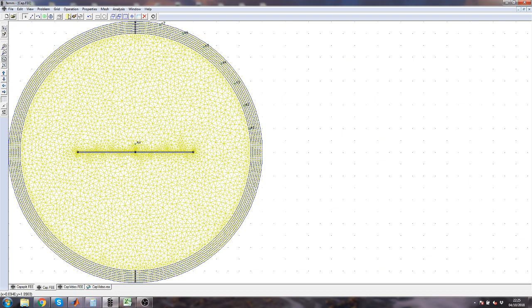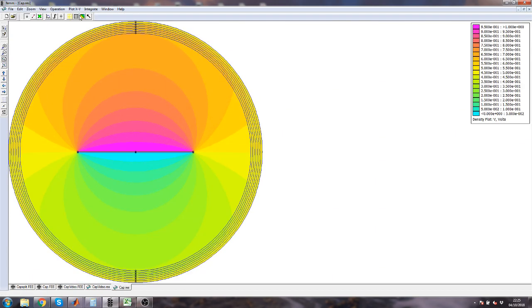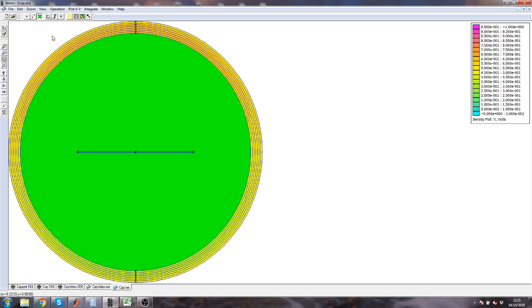So if you run the simulation for this one, I've already got it set up, so I just run. This is air, and the distance between the plates is 5 millimeters, and the plates are 1 meter by, at the moment, 4 meters in the direction into the page. And we can look at some data, and we could, if we wanted to, integrate for the stored energy, which is what I've been doing.